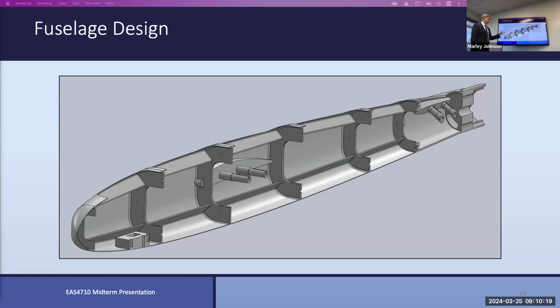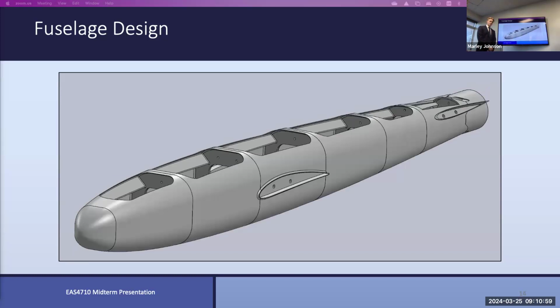This was our first iteration of it, and approximately half of this material was taken out, so I was able to make it considerably lighter after our first test. And then you said the wing spars would come in through those tubes. Yes, and we put a hose clamp on the end. The hose clamp is just going to go around this tube section. There's a little cutout on it, so it should be able to flex. You get the rod in the front, and then there's a slot that gives you this component.